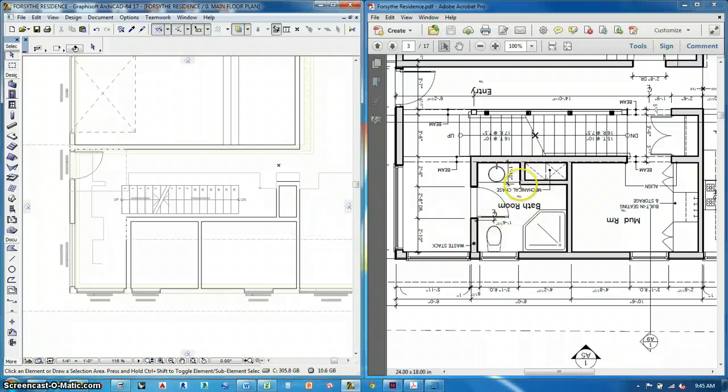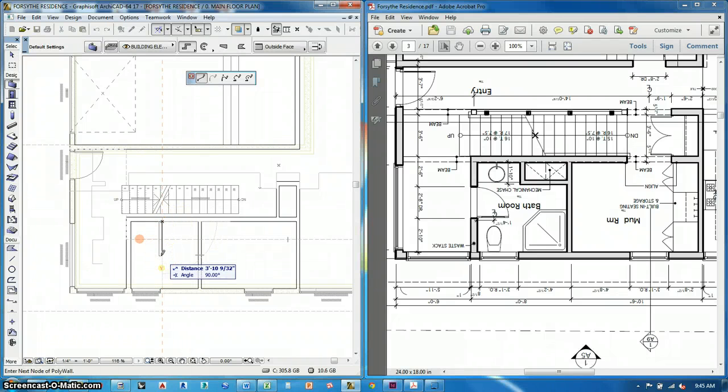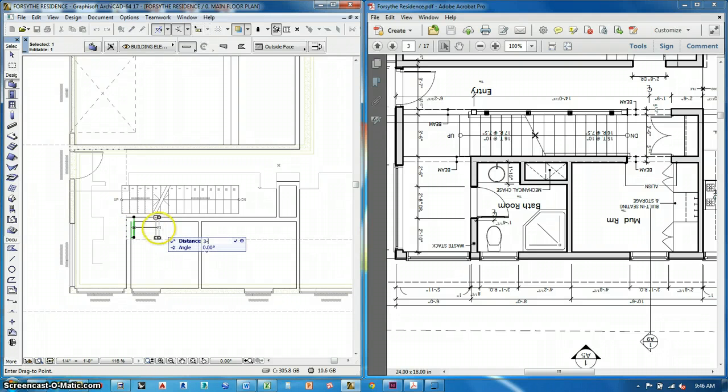And then there's this little 110, this little wall in here that comes down 1 foot 10 inches. I don't know what this dimension is. They're not giving it to me, but I'm going to presume that it's about the same as that rough opening. Let's call it 3'2". That might be dimensioned on an interior elevation somewhere or something, but we don't have those drawings.